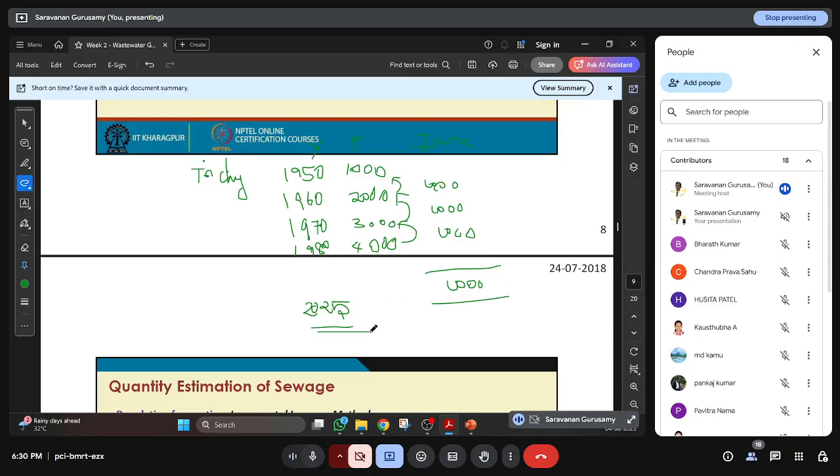So I need to know 2025's population. From 1980 to 2025, how many decades are there? 1990, 2000, 2010, 2020, 25. So 4.5 decades are there, right? Are you with me? Yes, sir, 4.5 decades. So if you multiply 4.5 into 1000, we get 4500. After 1980, for 4000 there is 4.5 decades of 1000 increase. So 4000 plus 4500 will give you 8500. That is the population of 2025. So this is based on the arithmetic method.